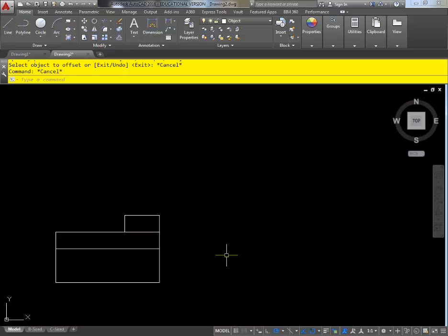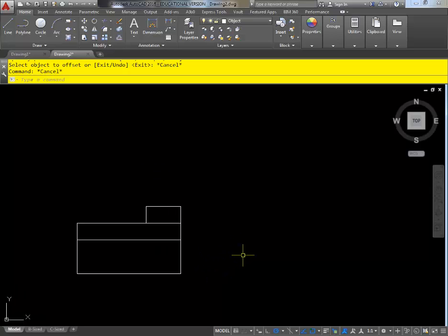So now I want to draw my right side view. Then I'm going to lay that out. Now how far you space them out is up to you. I will say that after we draw these, in a couple weeks, we're going to come back and dimension them. So I really want to leave space for dimensioning. I don't care how far away you go. Let's see, maybe I go, I don't know, maybe the other key is: is it going to fit in my paper space layout.